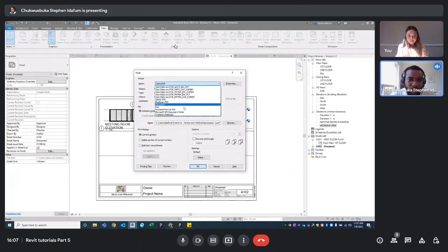So normally I use Microsoft Print to PDF. That's if you have the Adobe PDF. Or normally I just use Bluebeam. So once I have that ready, I want to make sure it's at the right scale on the right paper. Remember when we brought out the sheets, we did it on an 11 by 17, which is architectural B type paper. Now, in order to make sure that is good, we need to go to setup.